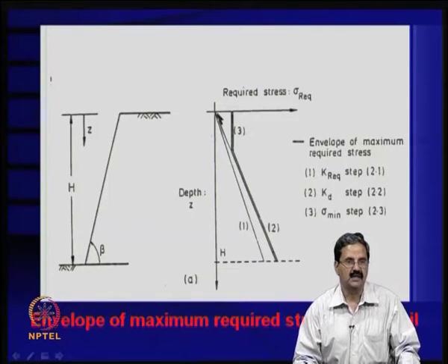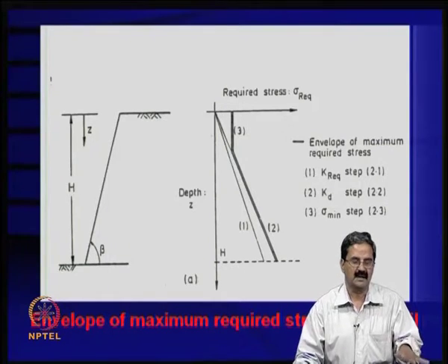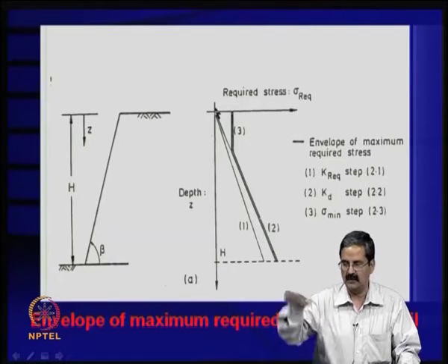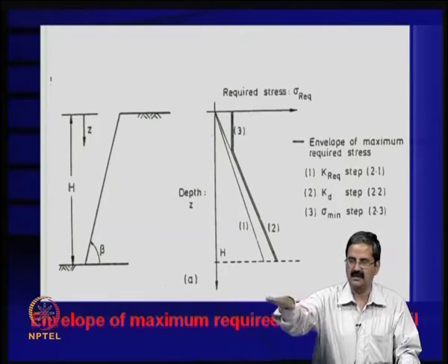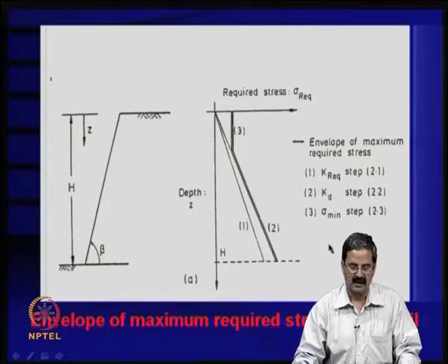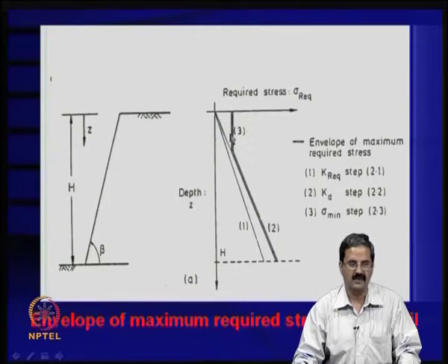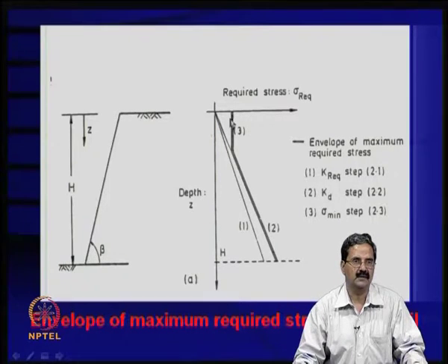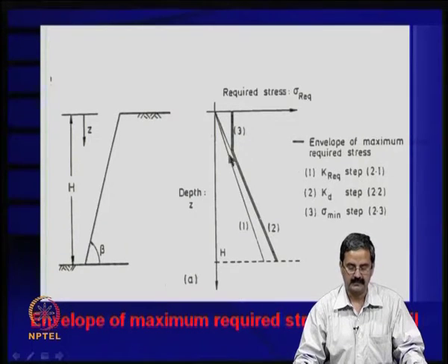Why? Because you have compacted it, and there is always some sort of earth pressure for which it has to be designed, because earth pressure is never 0 at the top. Actually we do not really compact heavily; we use simple compaction equipment like hand-held equipment, and we do some compaction here. Whatever it is, some compaction stress is induced, and to resist that compaction stress you should have reinforcement.